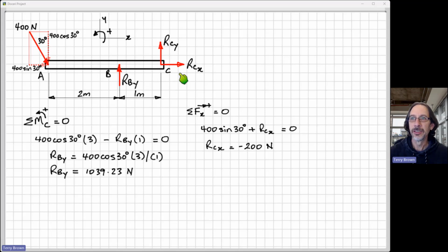Just leave it as it is. If you really want to end up with positive answers everywhere, start all over again, right? And work your way through. And that's probably a good check on your calculations anyway. Right? So, but yeah, never ever change your free body diagram halfway through because you get a negative answer, right? All right, so let's continue on.